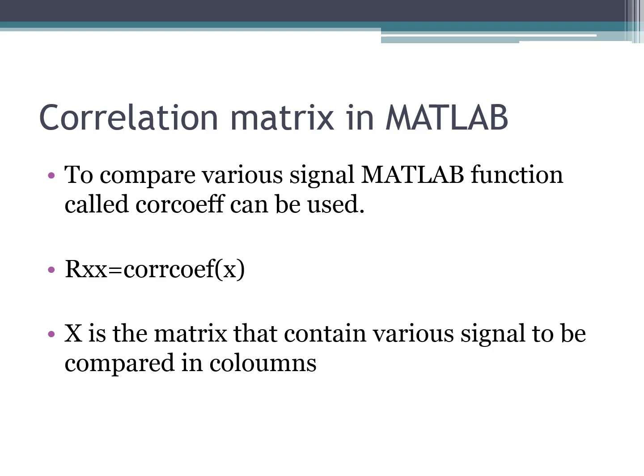Now in case you want to compare a number of signals, then MATLAB has a dedicated function called corrcoef. Corrcoef calculates correlation between different combinations of the signals. Here you can see X is the input to the corrcoef routine. X actually represents a matrix that contains the various signals to be compared in its columns.